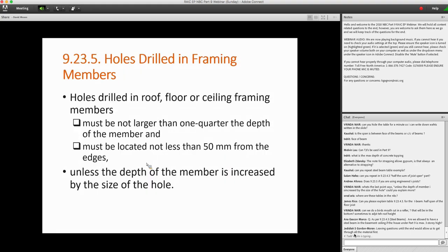Question of, does this hole drilling and framing apply to I-joists? So again, you'd have to look at the manufacturer's product literature to see where the holes can be made. Generally, it's the middle third of the length and the middle third of the depth, but they do have hole charts in them. Regarding notches in I-joists, not allowed. There are some limitations on that because the flange is where the capacity really is. And again, their product manuals would have a lot of that information.